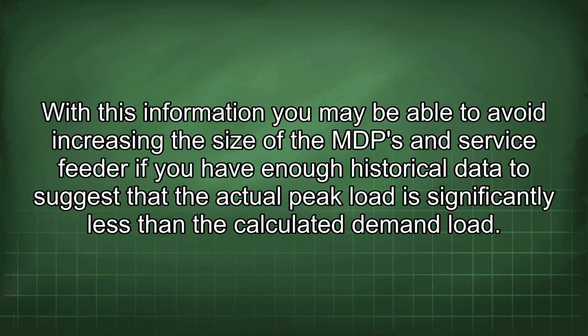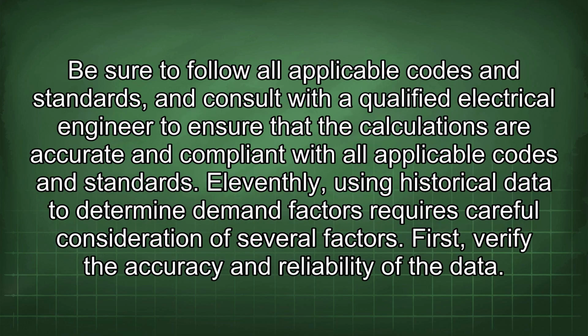With this information, you may be able to avoid increasing the size of the MDP and service feeder if you have enough historical data to suggest that the actual peak load is significantly less than the calculated demand load. Be sure to follow all applicable codes and standards, and consult with a qualified electrical engineer to ensure that the calculations are accurate and compliant with all applicable codes and standards.